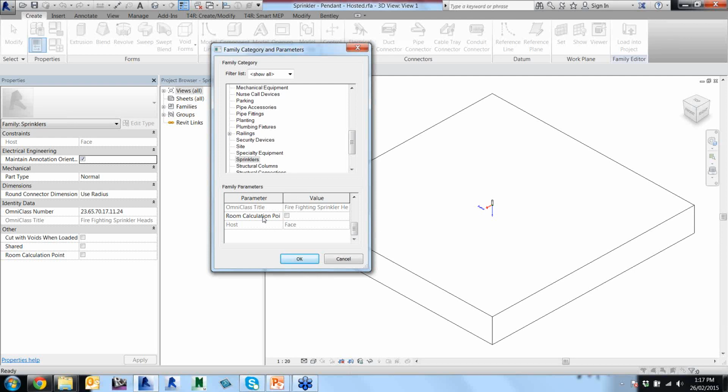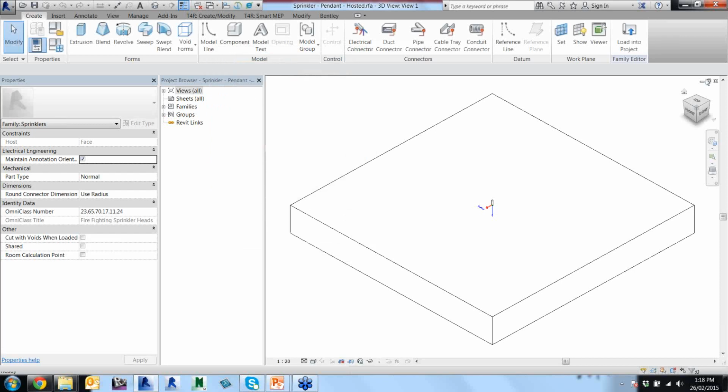So just be aware that if you're creating sprinkler families from scratch and you start from a face-based template, it's not easy to change those over. There are a few tips and tricks out there and workarounds for how you can get hosted families to be non-hosted. I think one of my colleagues, Klaus, did a webinar on that recently, where he covered some of those tools. But just be aware that it's not easy to do, so have a think about what you're doing when you're creating these families, whether you want it to be hosted or not. So this example is hosted.